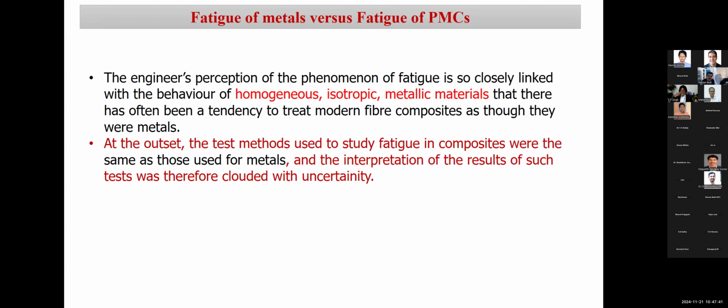Initially, when people started talking about fatigue of composites, as we already know, the fatigue behavior of metals has been studied extensively, and people are aware of much theoretical background. The experimental data is also immense. In the first instance, people tried to apply the same test methods, some of which are valid, like modeling using Weibull distribution, but the interpretation of the results needs to be taken separately.